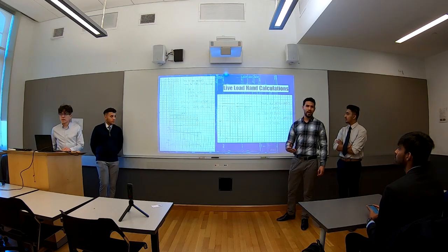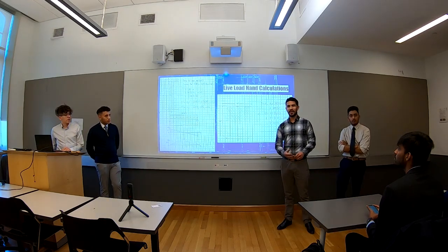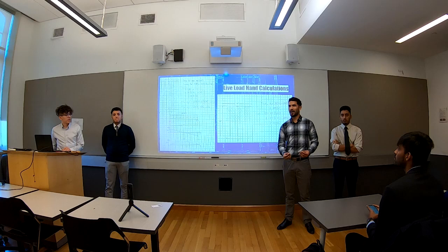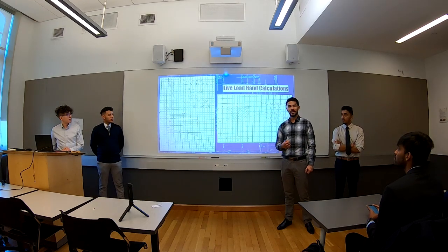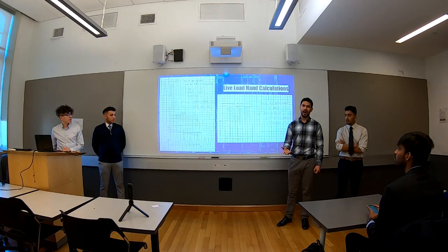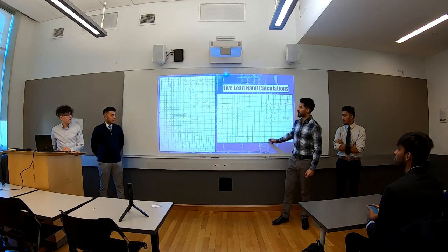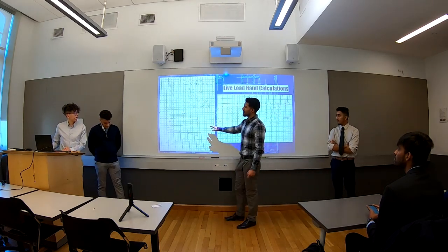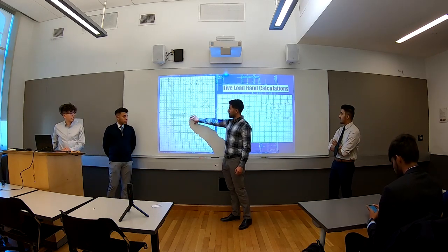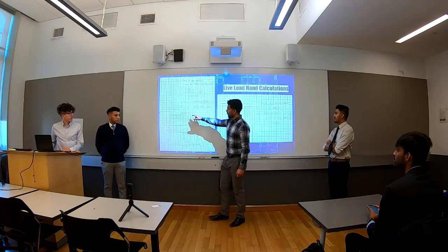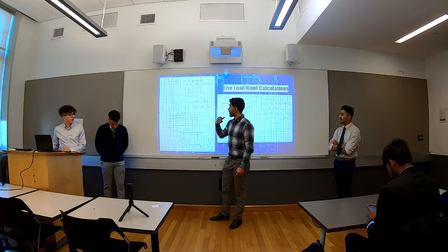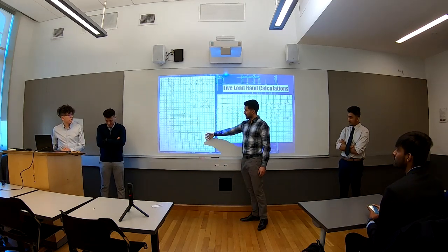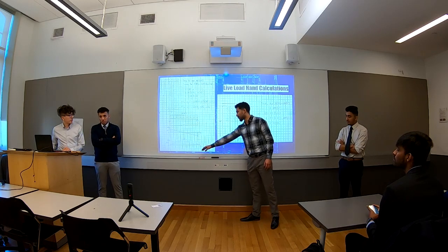As we know, computer models are a very useful tool, but they're not 100% reliable. We always have to confirm that the calculations it gives us are accurate and are going to serve the purpose that we need. So here we have the hand calculations of the beams, and here we have the tributary area of the beam that's going to be holding up, along with the analysis of the shear diagram as well as the moment diagram.